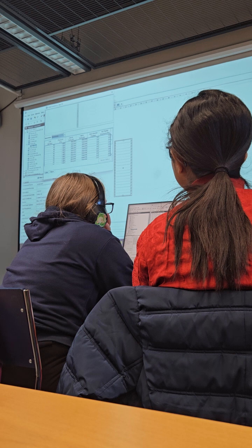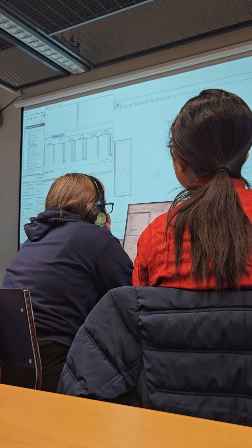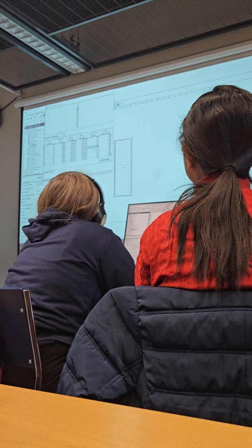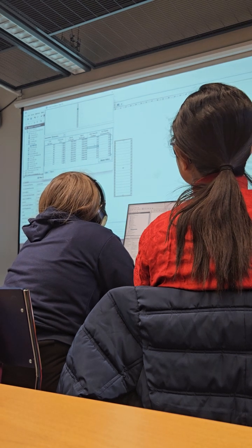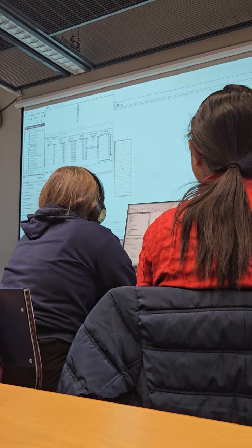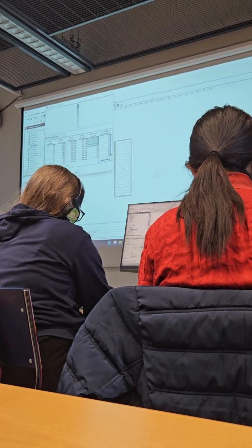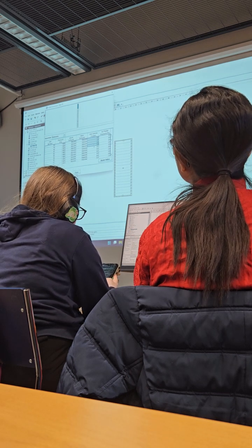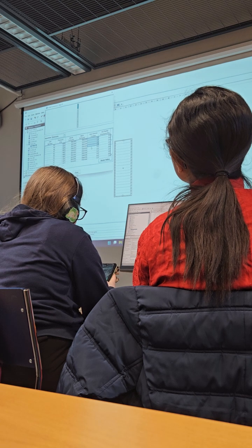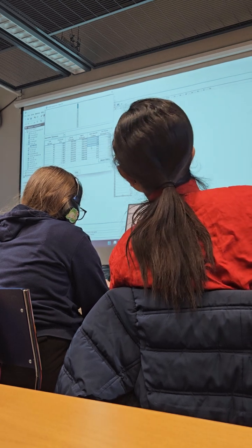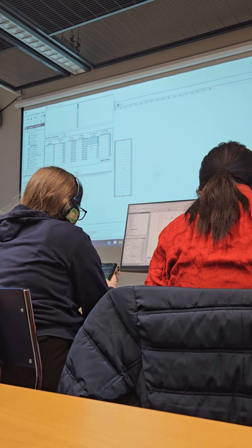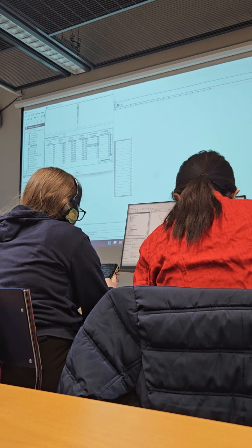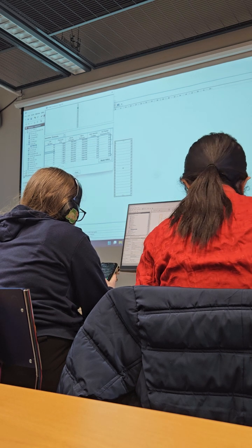Now we have valid conditions. But then, when we want to set the level somewhere, and we don't really know where it is now, but if we want to consider the level is somewhere, then we can put the gas volume fraction, which refers to the fact that it's steam there. Then we have to put the gas volume fraction to 1, so that we say that it's steam. I imagine that my top level is at this cell number 17.